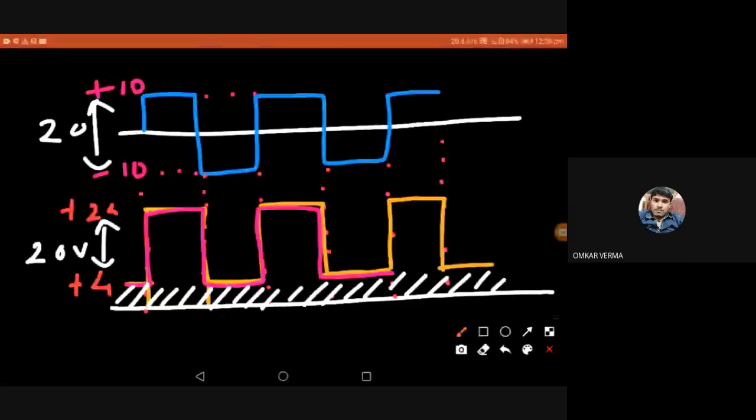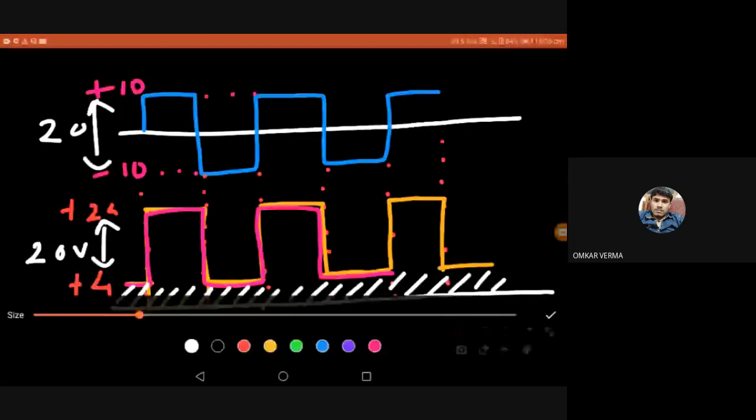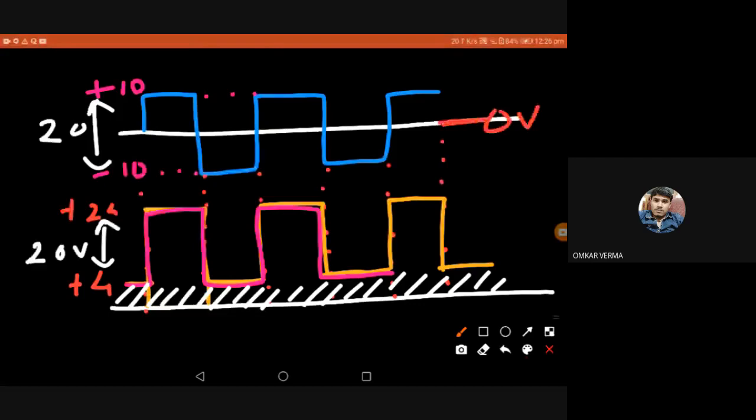Right? Initially it was the ground. You can see initially the ground was at 0 volt here. Now where is my ground? It is a symmetrical circuit, so it is 14 volt, with 10 on top towards 14 and minus 10 towards the bottom also. So I have given a DC shift of 14 volt because my DC voltage VB was adding on to the capacitor voltage. Is there any doubt about what we have done? The shape is remaining the same, but with a DC shift.